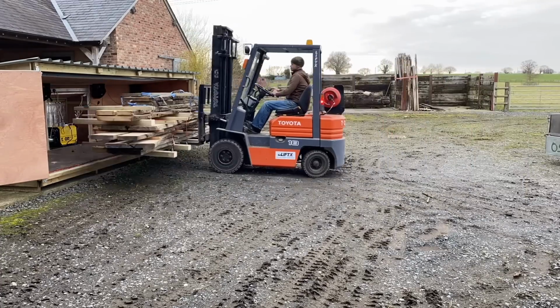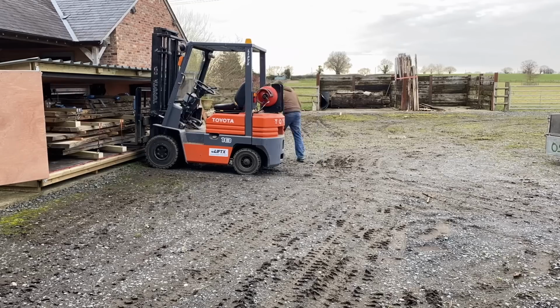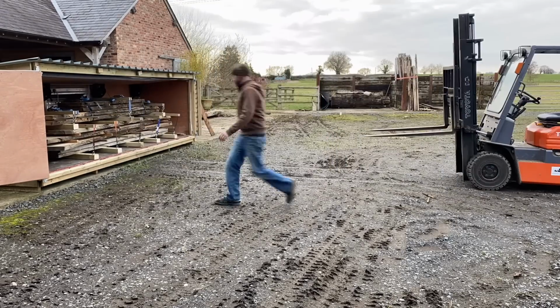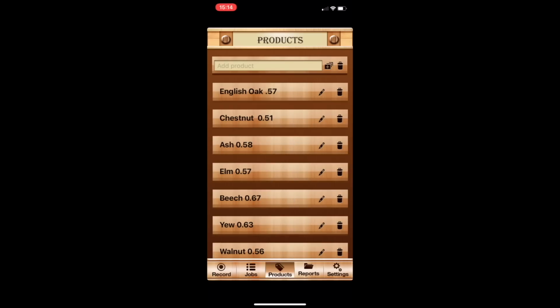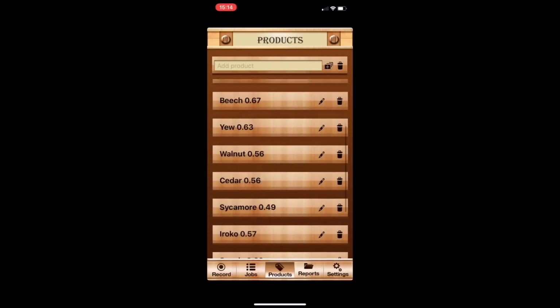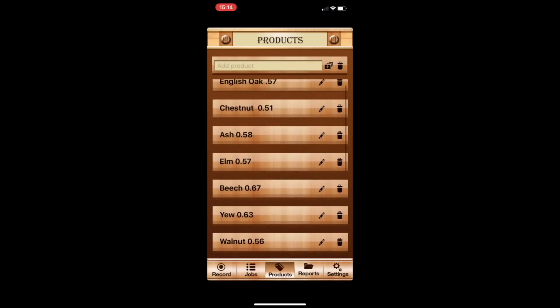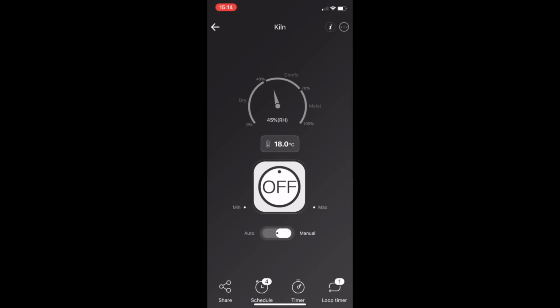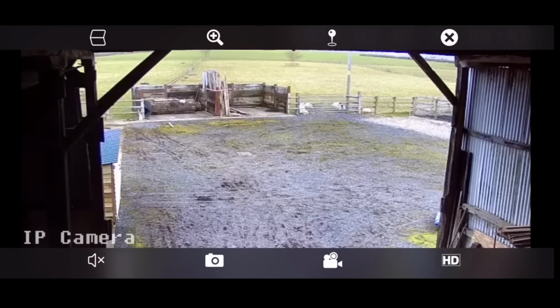But this is a game changer because again, I can just dip in wherever I am and see what the temperature is, and I monitor it over time. So every couple of days I go to my Wagner meter, ping in some readings for whichever project I'm on, change the wood type, then I switch back and keep an eye on that to see what kind of drying times I should expect, and I don't want to case harden the wood anymore. So those 2 things have been absolutely incredible. So with those top 3, and my workshop also having a relative humidity meter, etc., it's really been a game changer over the last 2 years.